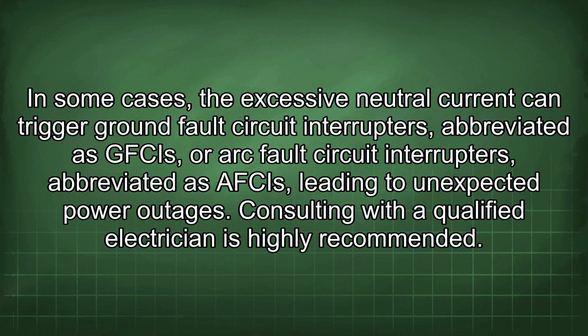In some cases, the excessive neutral current can trigger ground fault circuit interrupters, abbreviated as GFCIs, or arc fault circuit interrupters, abbreviated as AFCIs, leading to unexpected power outages. Consulting with a qualified electrician is highly recommended.